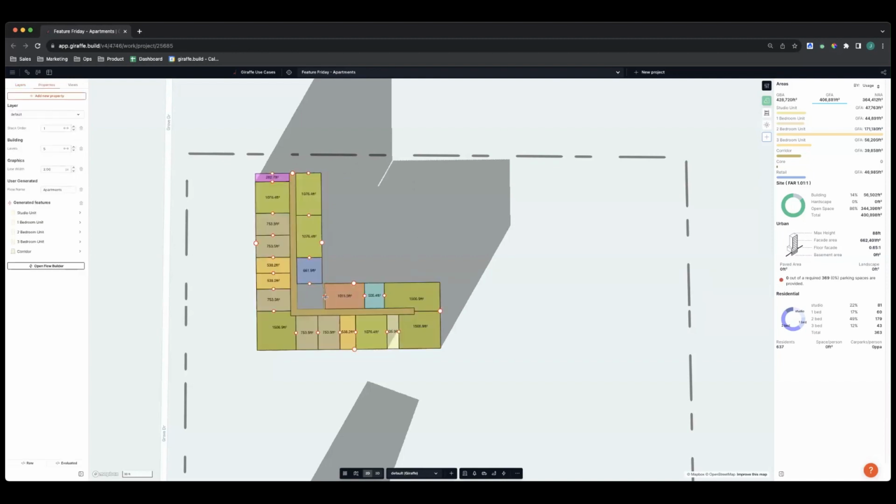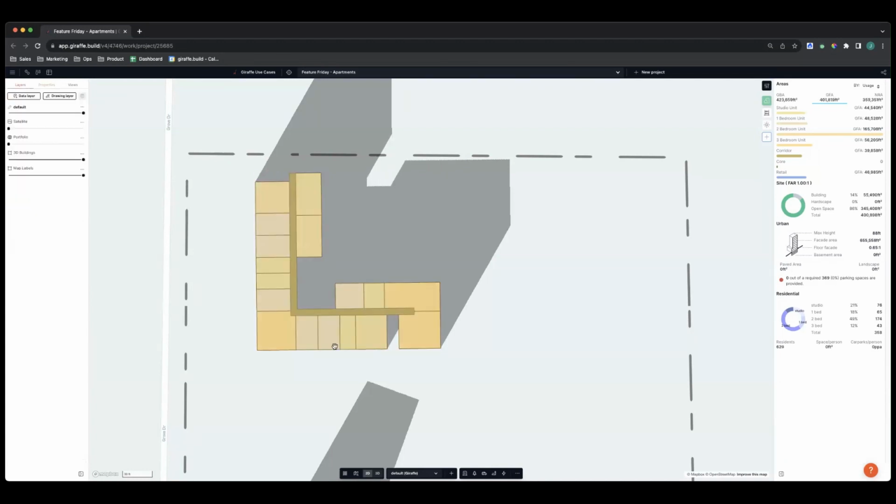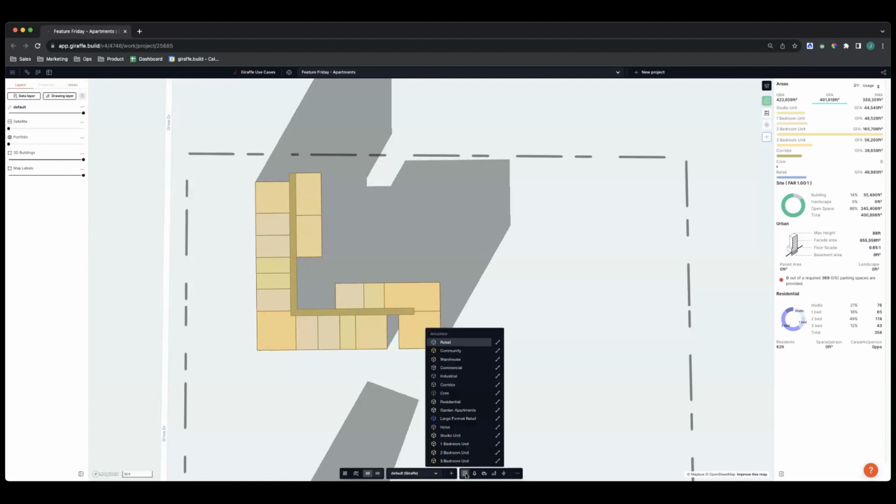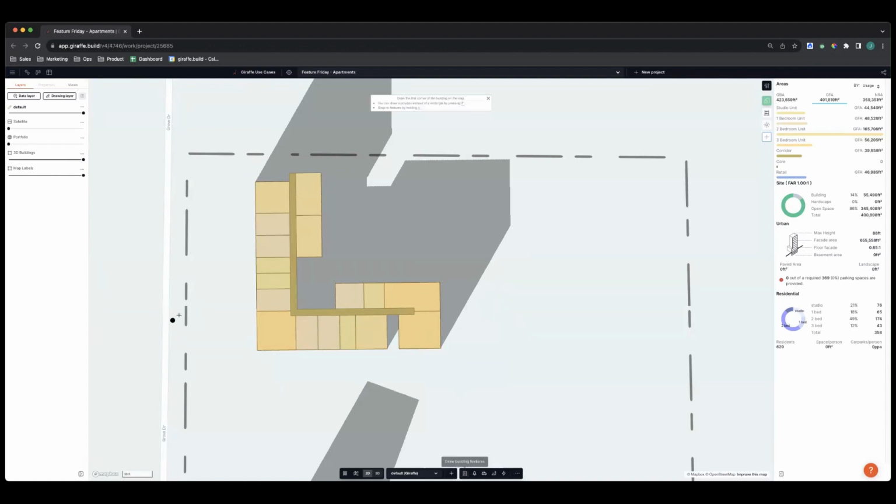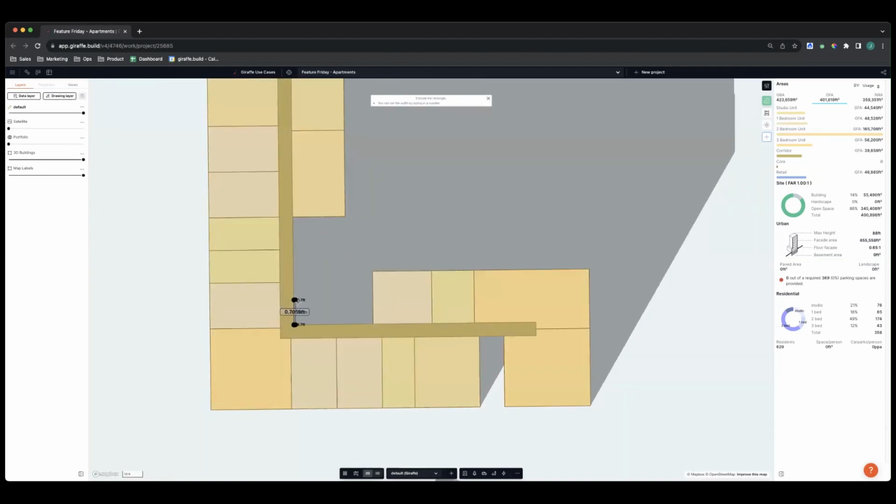Let's remove this guy. I want him to come back here, and we'll make him like a 700 square foot dwelling, something like 750. And this guy I'll bring back a little bit too. In fact, maybe we'll go all the way back on this one. And in its corner here, I'm going to draw a usage that's not connected to the algorithm. I'll go up 12 feet. I'm just typing 12 on my keyboard, and then out 12 feet. And I'm snapping to the corner here and then using the set lengths on my keyboard to keep it exactly 12 by 12. And now I still have these voids.